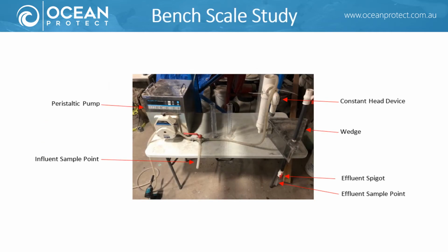Phase 1 of the research project was to identify the best performing media in terms of removal efficiency at different flow rates. This was completed using a 1/24th scale of the radial flow treatment technology. Influent water was diluted to 1 microgram per litre of total PFAS using contaminated water from the field study location. This water was pumped through the bench scale test over 30 minutes with 6 150 ml aliquots taken every 5 minutes for the influent and effluent water.